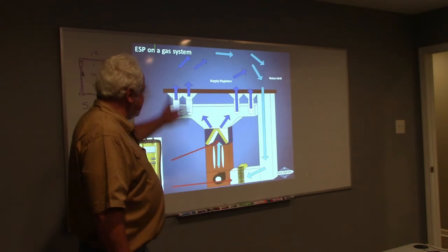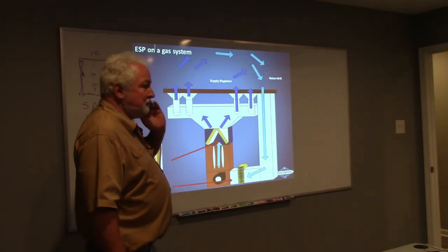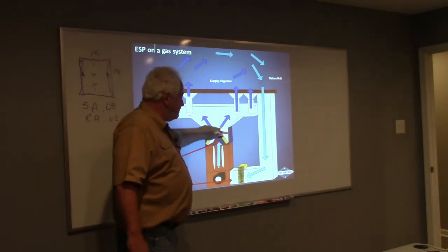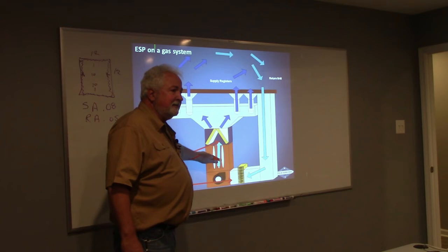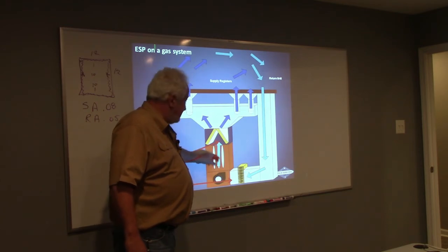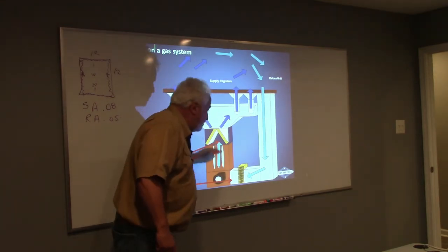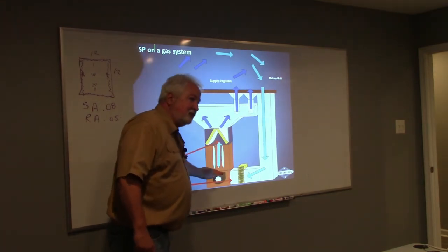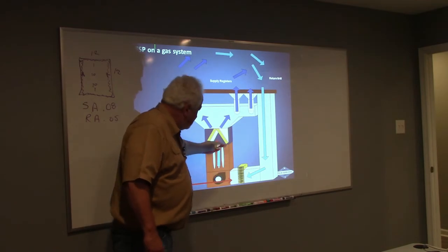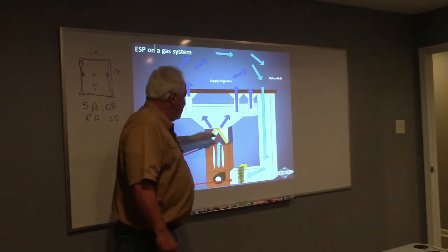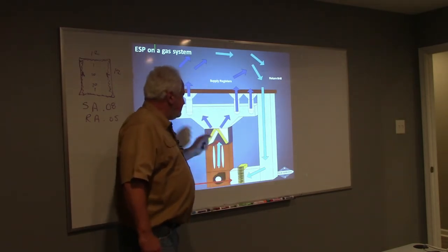Okay, so let's look at, here's an upflow gas heater. Do I have to go between the gas heater and the coil? Yeah. Why? Because they're separate. I want to go total external to the cabinet that has the blower in it. Yes? So here and there. I need to figure out what that static is on there as well.